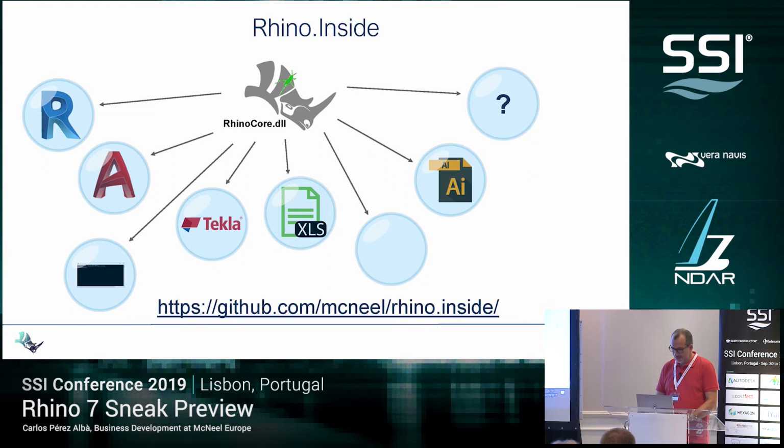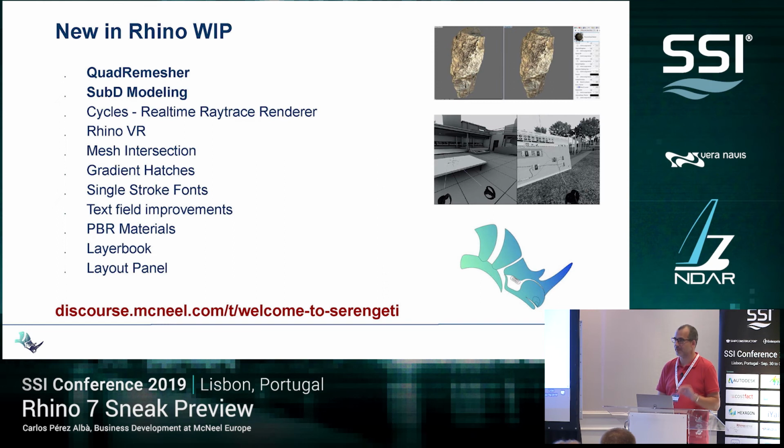In this case, you can see in this screenshot that we have a Rhino model, and just with this component in Grasshopper, it automatically shows the Rhino model inside Revit. This works for any kind of geometry in Rhino, and this is really live. Other examples. Here, for example, we are using Revit geometry as the input, okay?